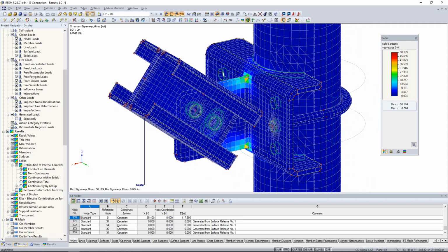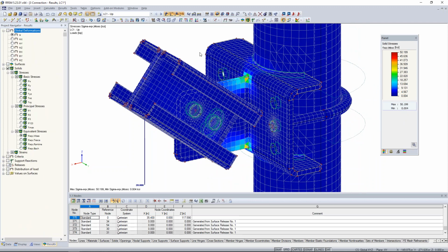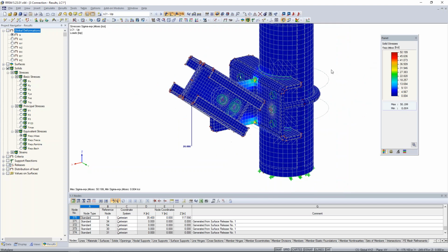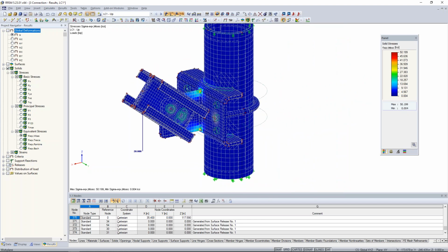Well, with von Mises stresses this high, I think this would immediately flag us that we probably need to run some type of plastic analysis. Remember, the material for these two plates is A36, so our yield strength is only 36 KSI, yet we have stresses clear up to almost 50.2 KSI. So what we'd like to do now is to take advantage of one of those nonlinear material models that we discussed back in the PowerPoint.